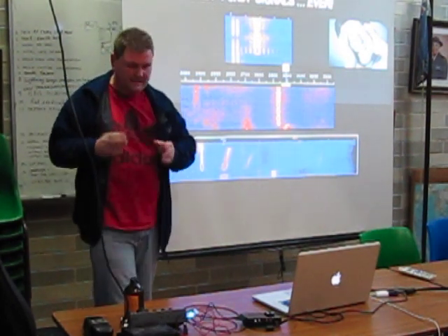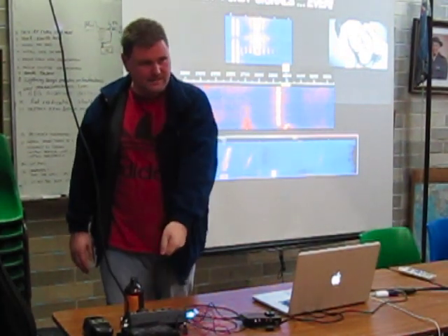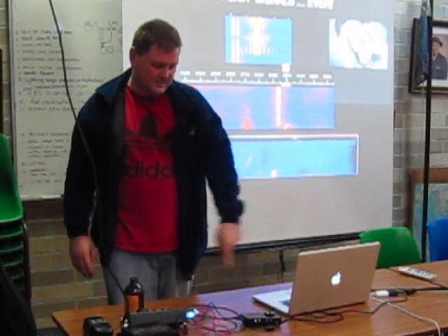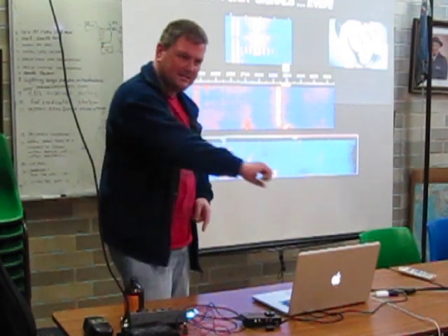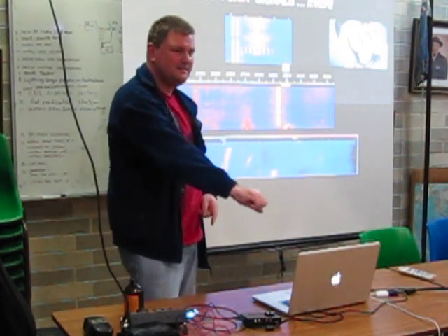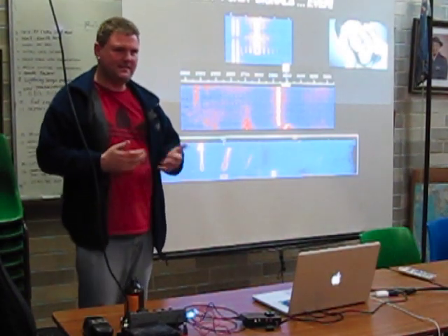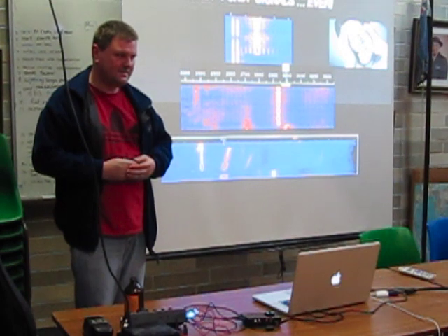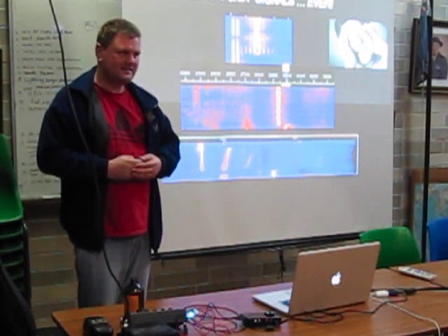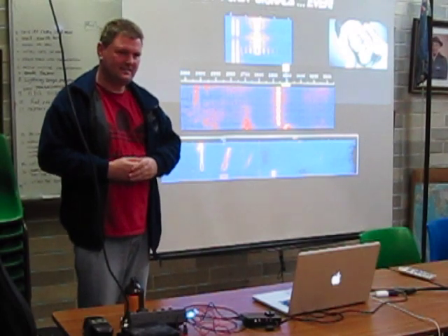Yeah, I should actually mention that. You actually don't need any physical connection at all. If you've got a microphone, put it next to the speaker of your radio, and then you can decode on your PC, and you hold the microphone of your radio up to the speaker on your PC and transmit. I'd say that there's more chance of having a dirty signal if you do that, because you get echo from the room. It's just a simple 3.5mm cable, socket to socket, and you're away.